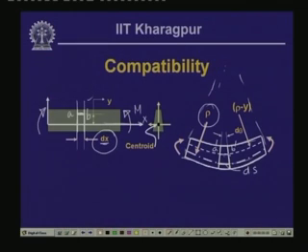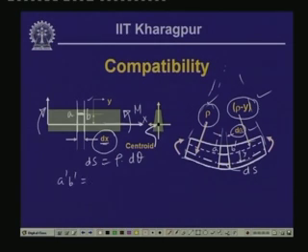Now, here this was at a distance of y, also undergoes deformation, and let us assume that this particular segment forms an angle d theta. Hence, the radius of this particular arc is equal to rho minus y. So, this is rho minus y. Now, this particular distance ds from the radius rho and this angle d theta, we can write as rho d theta, and the segment distance A dash B dash, we can write as equal to (rho minus y) d theta.